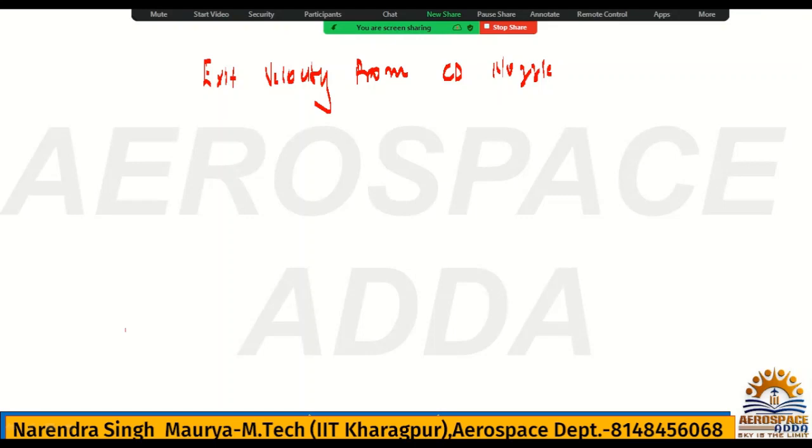but in that, if you go, then pressure will be cancelled out. Why? Because it is fully expanded, no? So exit pressure and atmospheric pressure will be the same, so that value will be cancelled out. So that is one way to calculate the exit area.